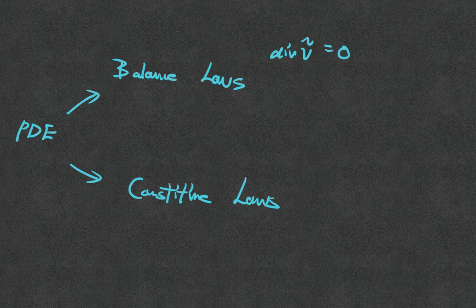If I take account of all the different orthogonal directions of change and add them together, there should be no change at all. If you look at this cube and assume there's an in and out in all 6 directions, and I add all the in and out directions together, I get nothing, meaning that I did not create mass, I did not destroy mass.